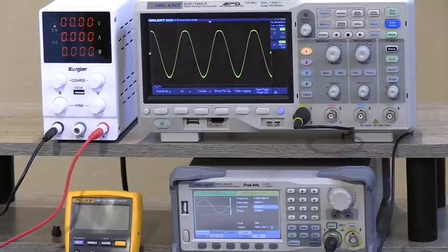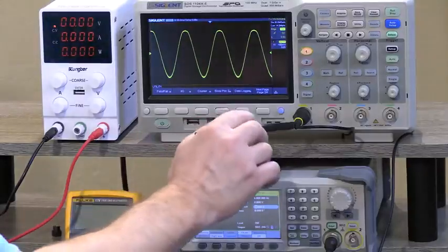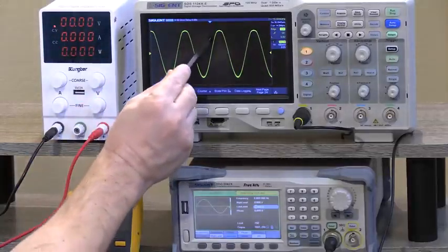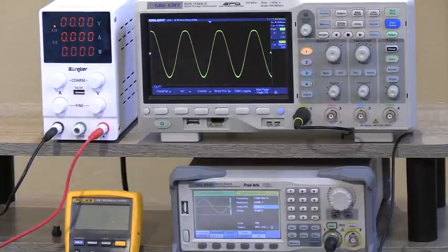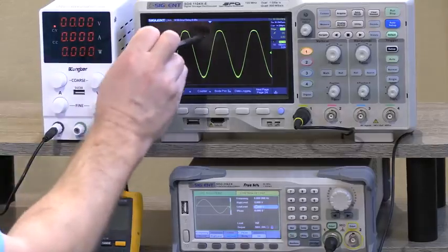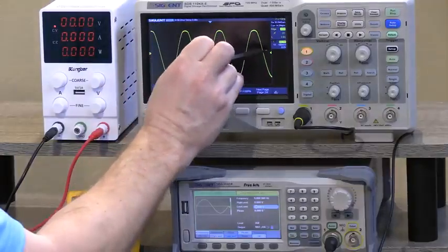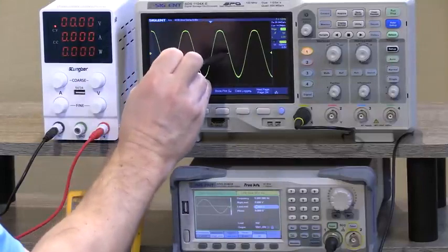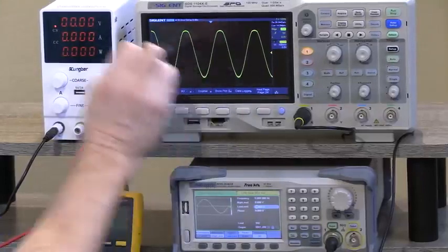What's happening here is that basically inside of this conductor, there are actually two wires, right? You can see the two wires are connected over here. And what it means is that when I'm going up on the positive side, the red wire here is going higher and higher and higher in voltage. That means the current is coming into the circuit through the red wire. But eventually, the voltage drops back down to zero. Remember, this tick here is the zero axis, so it goes back down to 0 volts, but then it switches to negative voltage.